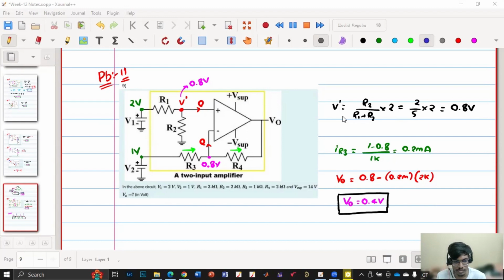What I'm thinking is, for dynamically changing V2, the output voltage depends on V2 minus 0.8, so the current value changes. And on the top side also, if I push this V1 nearly to the supply voltage, then it will be acting as a comparator, since it is already saturated. So from there onwards, is it possible to have oscillator behavior and comparator behavior in the same op amp?